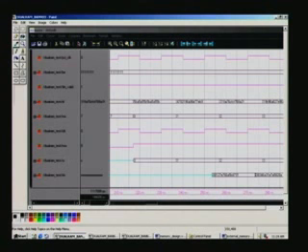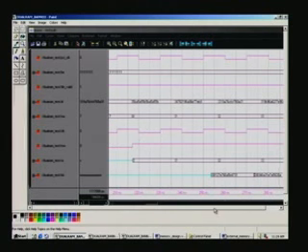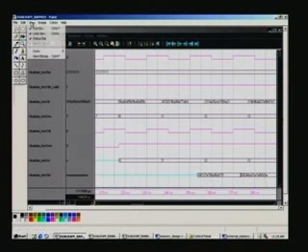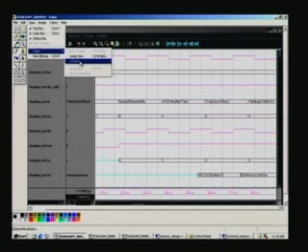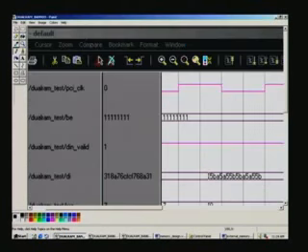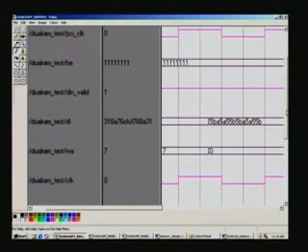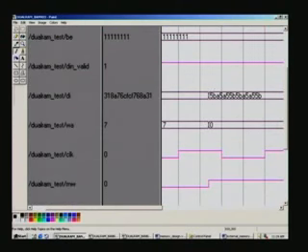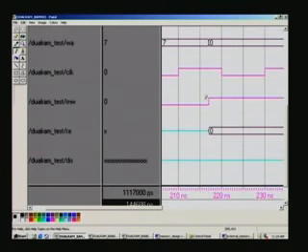And now you see that the read address has become active, and R and W has switched over from 0 to 1, and this is the system clock, and you can see the very first data here, and I will zoom it so that you can read. You can see here it is continuing to write with the write address changing, so it is going to the next block writing, and concurrently you can see R and W switching from 0 to 1 to write into the second RAM, and concurrently to read from the first RAM which has been filled prior to, and D0 output is this one, read address and this.